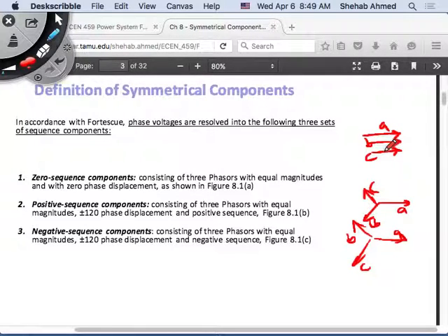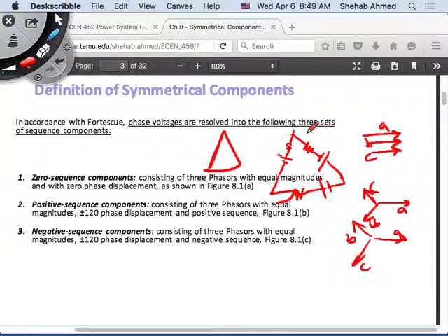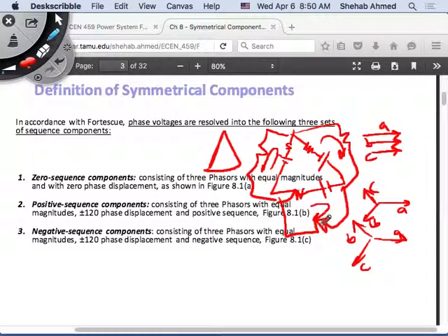Remember when I was talking about the delta, the current in the delta? Remember at some point I talked about the current in the delta, and I said that, let's assume that we have a delta here with impedances and I have loads, three-phase load connected to the delta. What did we say here? I said that there will be current, of course, flowing in these loads, but there will also be, if you do Kirchhoff voltage law around this loop, it's this voltage plus this voltage source plus this voltage source. They're all in the same direction, right?